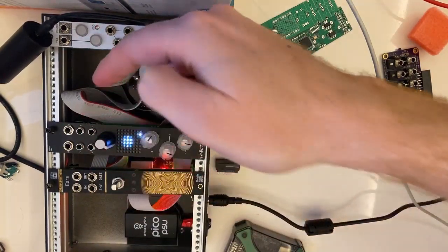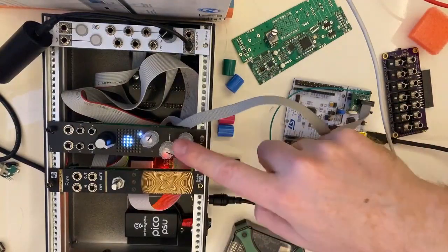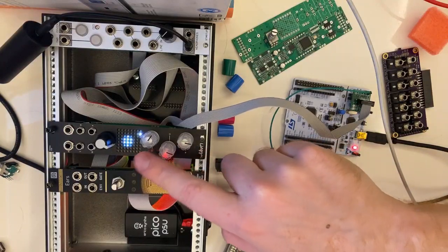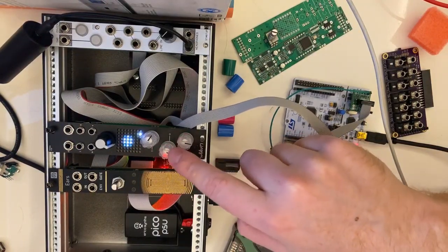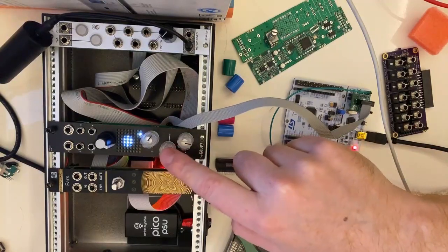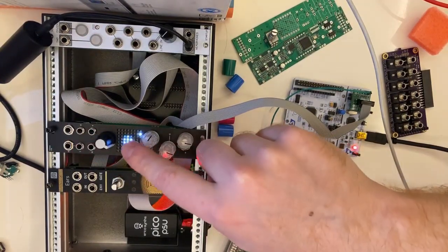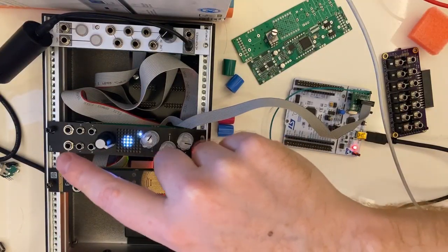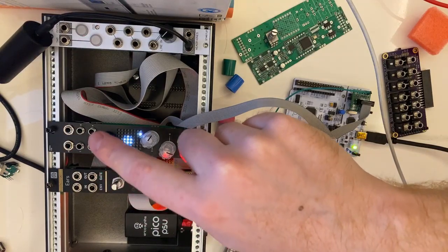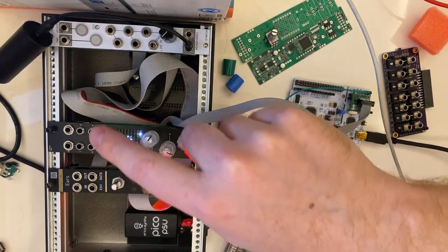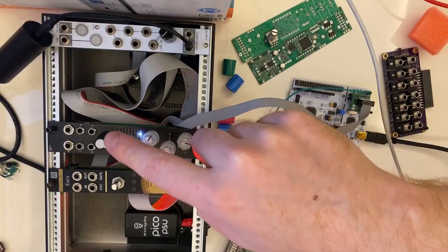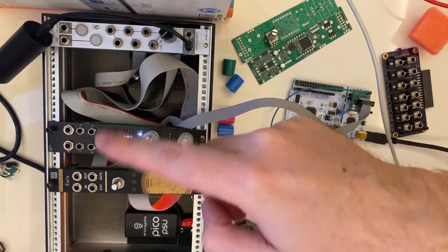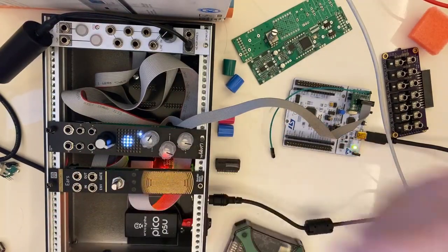The idea is I've got 3 CV inputs, A, B, and C, which correspond to these 3 knobs, although they're not electrically connected. They're separate ADC channels, so that the software can decide if they're a scale or an offset or whatever. So 3 CV inputs, a mono audio input, and then stereo AC coupled codec out. And in fact, the top 2 jacks are both connected as stereo and as ADC. So the STM sees it as a CV, DC coupled, and then the codec sees it as audio. So you can actually do stereo in, stereo out, or mono in, stereo out.